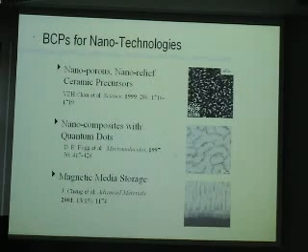In this case, I have another examples using the block copolymers. I put the three more examples here. So block copolymer can be used as nanoporous, nano-relief ceramic precursors. In this particular example, people use the silicon-containing block copolymers. So they just use the self-assembly using the polymeric property. So the polymer is self-assembled, then make the three-dimensional bicontinuous structure, and then did the heat treatment.